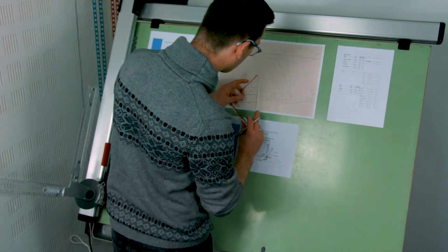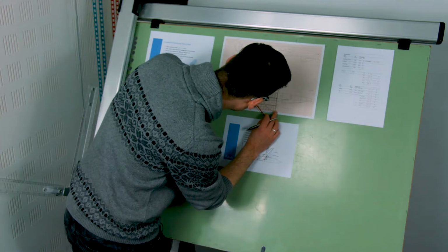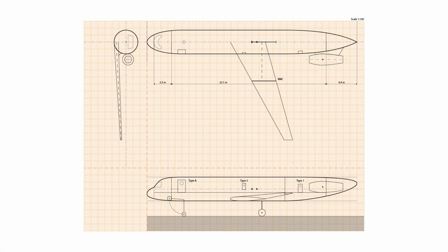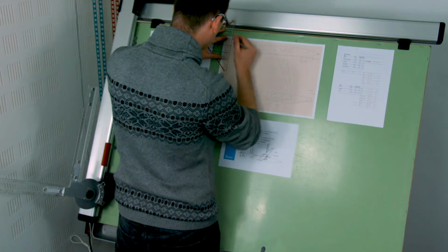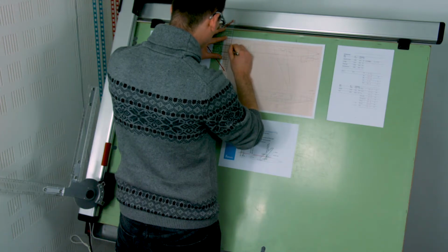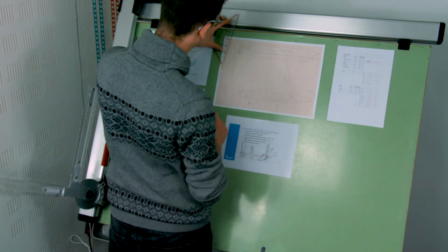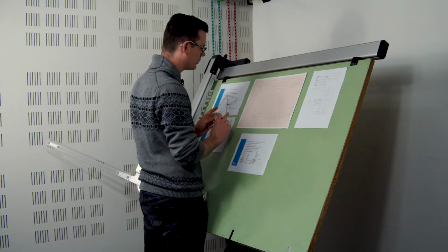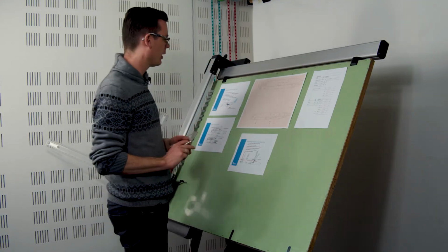Next thing is the height. So with respect to the center line of the airplane, the wheel is about 3.5 meters below the center line, and both wheels, well, that's the main landing gear wheel axle that I just drew in. Again, I'm using a dashed line here because I don't really know where it's going to be yet. I do know where the nose wheel is going to be. Already computed that we're going to have two nose wheels.